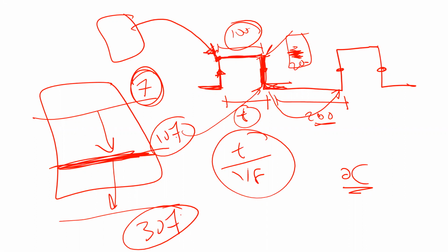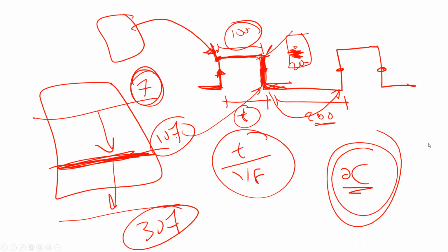That's how it is. So let me tell you the conclusion before. Again, all of that is just the big picture. I'm going to give you the details right now. Number one, why does output compare need interrupts? Output compare needs interrupts because in every interrupt, as you see here, guys, I'm going to say how long this one has to stay high before you toggle it, or how long the 0 should continue until you toggle it. So in every interrupt, you have to determine this value, right?